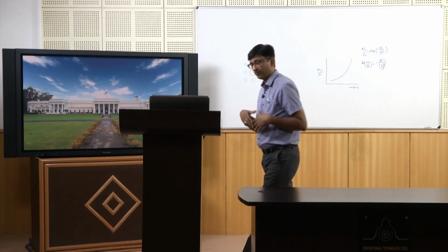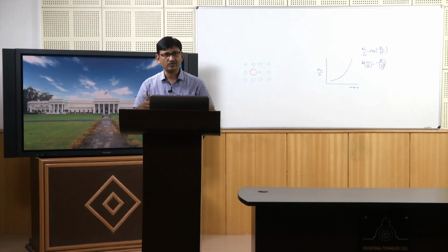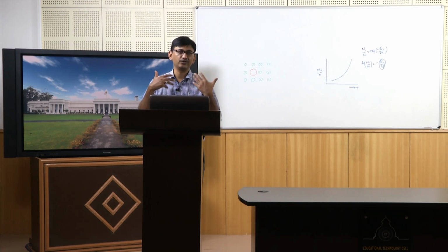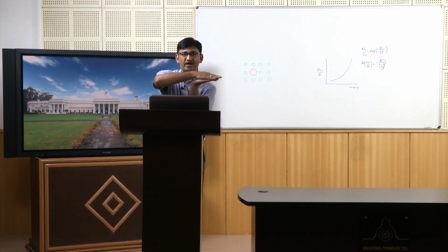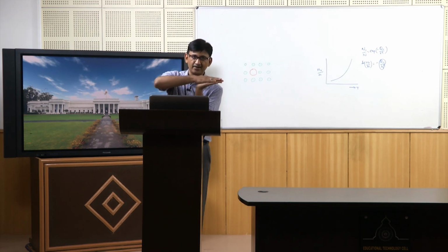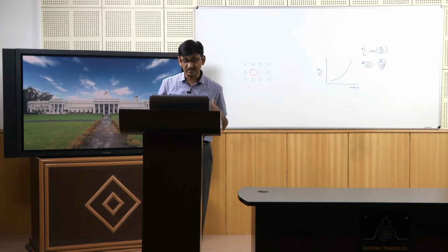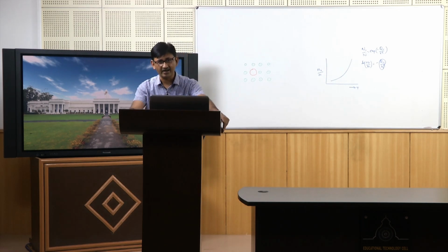Okay. So, the forces which people found out were much lower than what you will calculate by doing this kind of movement, okay, where all the atoms are taking part in the sliding process together. Okay. So, all bonds will be broken and new bonds will form, and this will require very high energy and very high force, but the measured force was much lower than that.